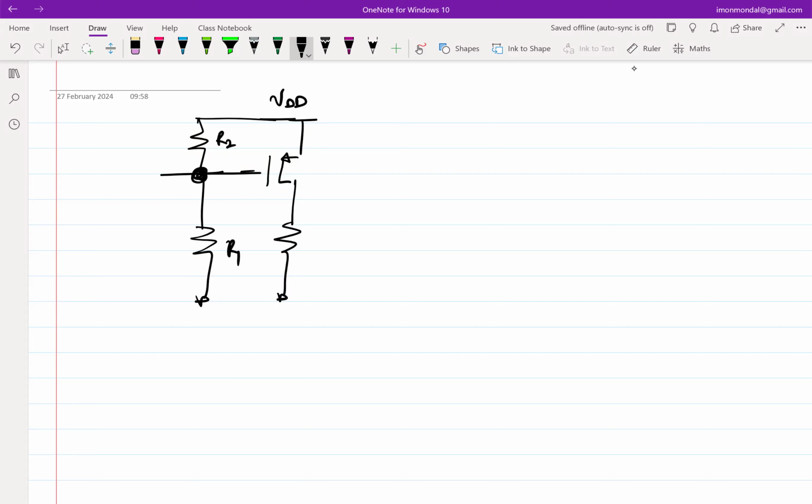And then we also saw that if we connect directly an input here, this will not suffice simply because the quiescent voltage at this node will go to 0 because the quiescent voltage of the input is 0. So one way to go about fixing this issue was essentially to put a capacitor. If I put a capacitor here, in the absence of an input, the capacitor automatically gets charged to the requisite voltage value, which was in this case, I think 2 volt or 3 volt. I don't remember, but something like that.